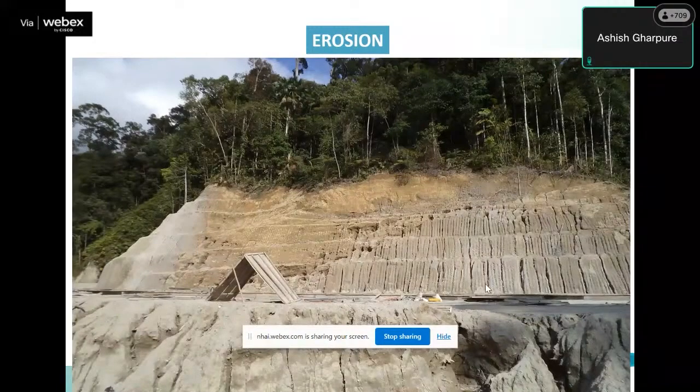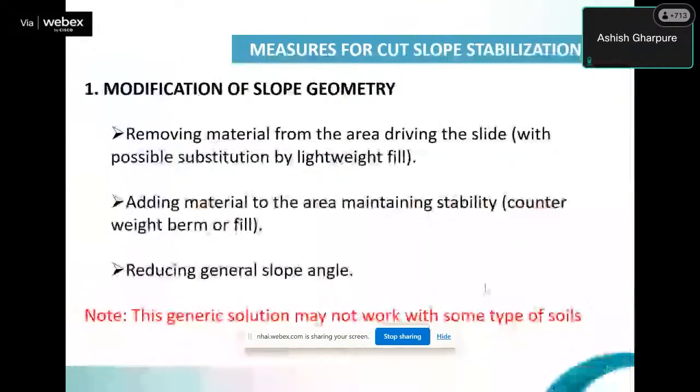So this is just to show how grave an injury erosion can cause. This is a project site we had in North Sumatra Island, Indonesia, where you can see the gullies getting formed, and not only that, bottom right, big sinkholes are getting created because of subsurface flow. Even an elephant can go into that. And this all happened within a day when I was there, when the cut was open and heavy downpour happened, and then these kinds of failures started. Next, please. So erosion has to be taken seriously as well.